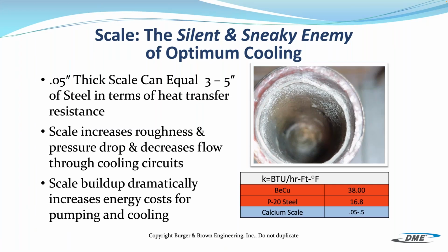So to kind of go back around, your cooling cycle is anywhere from 60 to 80% of your total molding cycle. So optimal cooling is critical to be able to reduce that and create good part quality. Some of the inhibitors to the cooling are design, which is very critical for the designers of the tools to understand turbulent flow, to make sure that they can design the cooling circuits correctly and optimally, to make sure that we have the good parts in the end and set us up for the best manufacturing process.